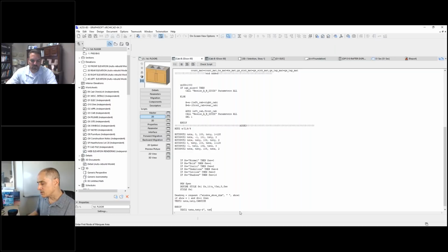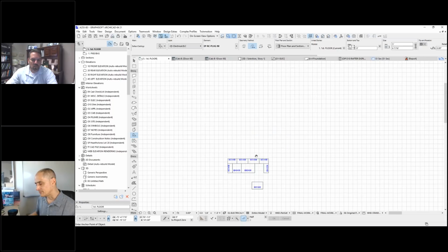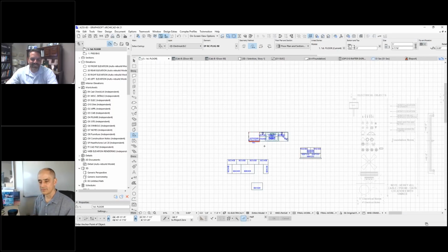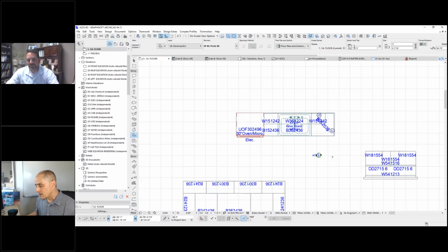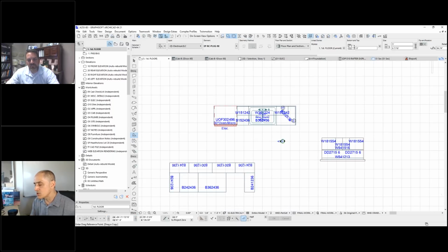Go into some other question. Dave Olafs, you were placing electrical outlets. It looked like with one move you were able to rotate them 90 degrees. How did you do that? Hotkeys. D I use for drag. R I use for rotate. Okay, so basically it's the rotate command, and you didn't see him select the command, he just used a keyboard shortcut. Correct, keyboard hotkeys.